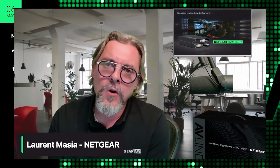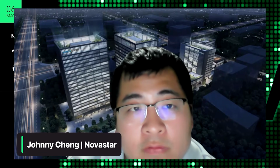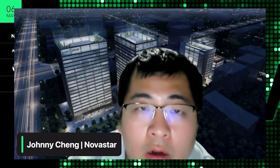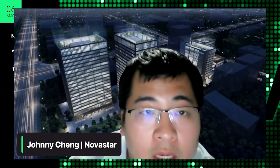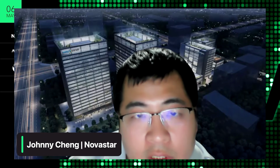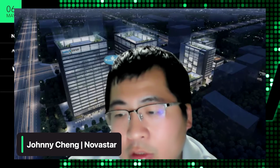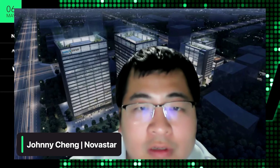But on the Novastar video wall, for the output cables, how long are the cables? How does it work, Johnny? Actually, if you're using Cat6, we recommend it for 100 meters, just for the network cable. Over that, we recommend that you use fiber to make the transmission. For the fiber, there is no real limit. I think it's 10 kilometers maximum for sports.